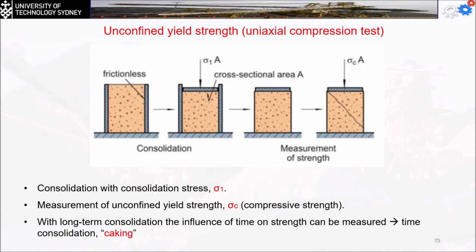With the long-term consolidation, the influence of time on the strength can be measured, which is called the time consolidation, which is the caking. Now, the time consolidation doesn't have to add an extra load on the material. Its own weight is going to cause the compression. Within time, the material will be compressed down and built up, and that's what we call the caking. It's like when you leave something for a long time in a jar and you cannot take it out.